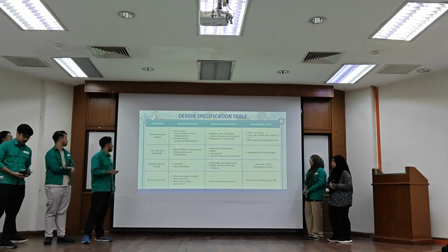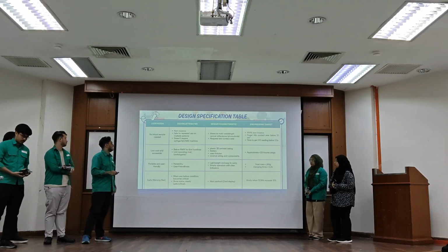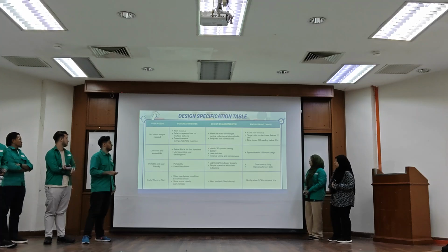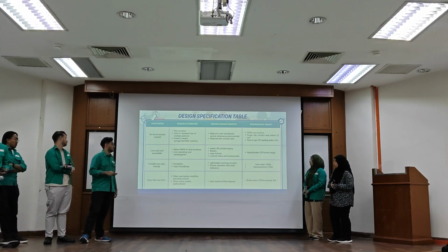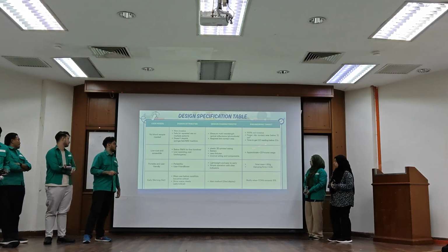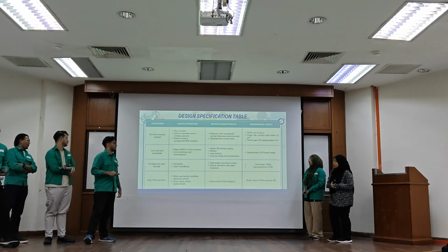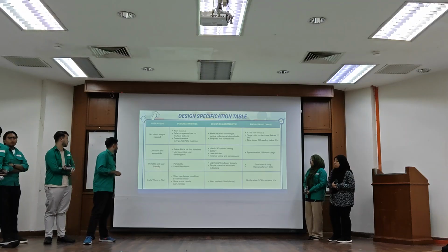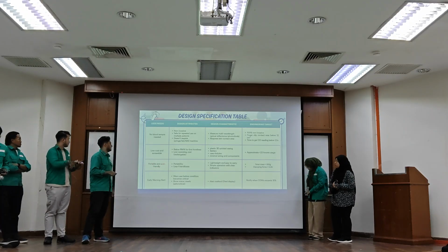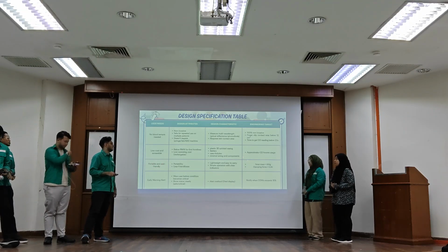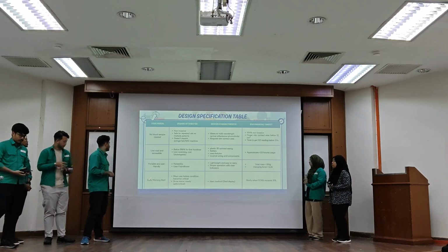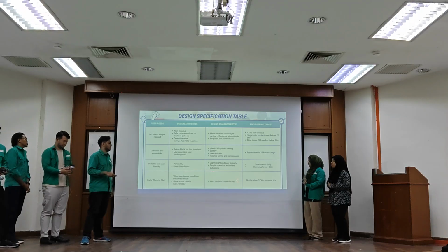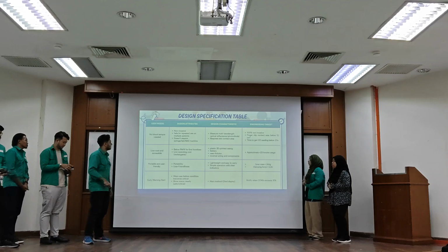Next, low cost. We are targeting to commercialize it below 1,000 ringgit. And how is the design? We use a 3D printed casing, battery, Arduino, and minimal wiring components. Our engineering target for this is for the battery to last about 23 hours of continuous usage. Next, it's portable, which means the engineering target must be below 150 grams, and the clamping force is 0.3 Newton. The last one is the early warning alert, where the COximeter will give a warning when COHb is high.